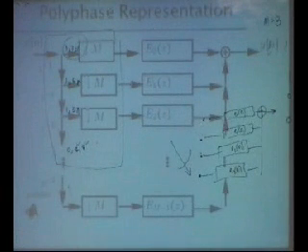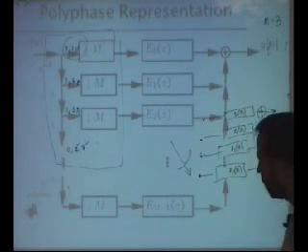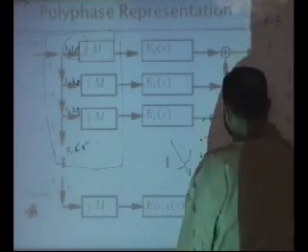Okay, so this is what is happening. A switch is working at a fast rate. All these filters in parallel are working at slower rate, but they are doing decimation. You are not throwing away anything. Automatically that has been taken care of. So this is the polyphase decomposition. I'll show you the MATLAB code for the decomposition, and just to show the equivalency of